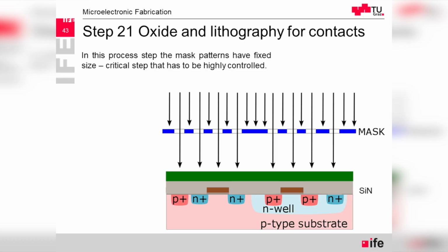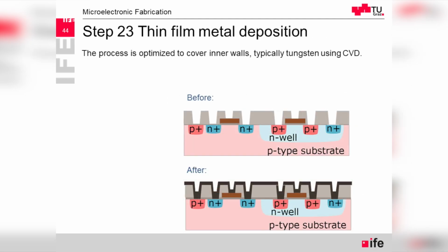And the next processing step, photolithography, defines the patterning of where we have the contact. So first, between the silicon and the first metal layer is called contact. Then between all the following metal layers, the connection is called via. Even though they are made quite similarly. So next, we have this deposition of the contacts.